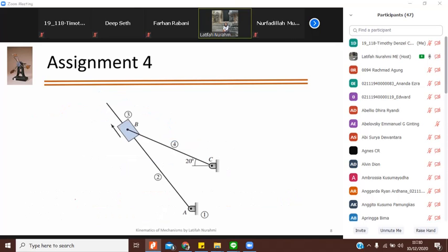Draw the kinematic diagram. This is also tricky, but by practice, you should be able to do it by yourself. And also you have to be very detailed for this. What I mean by detail: point A is not on the same line as point C. You see there is an offset here.